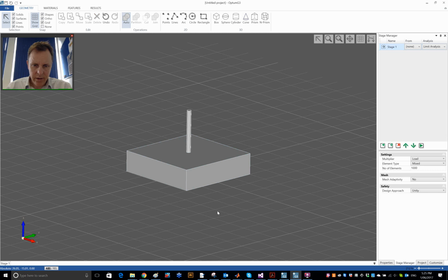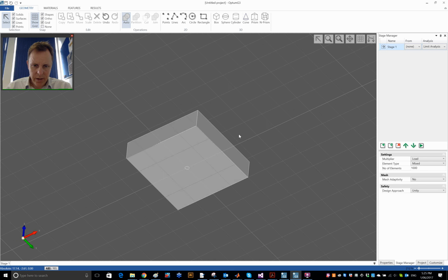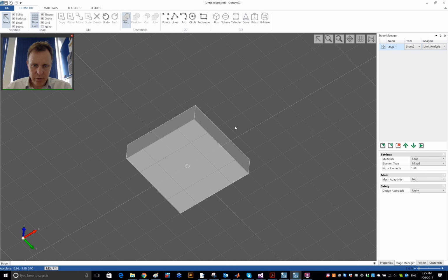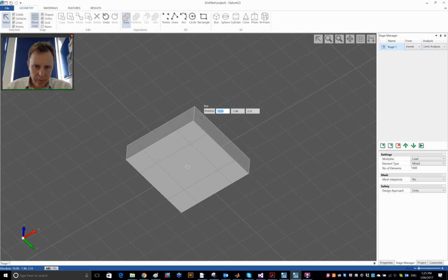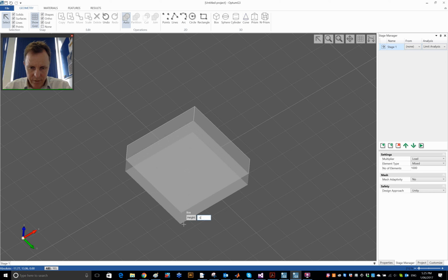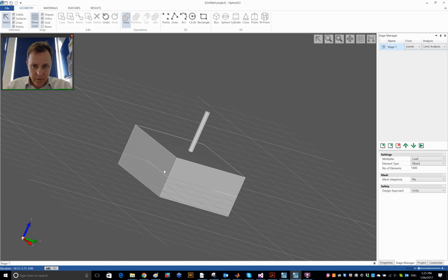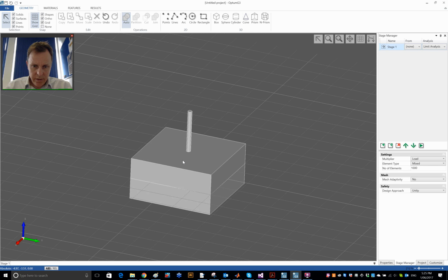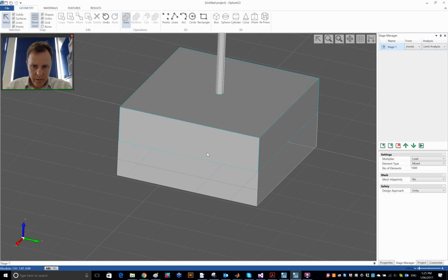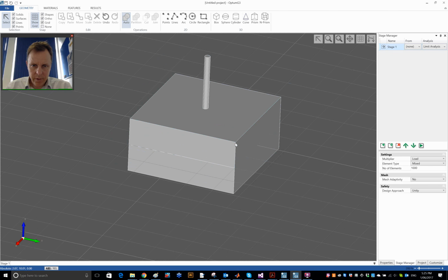the soil, and you should be able to see the base of the pile. And then we would want some soil here as well below the pile, and again I can make that to a depth of 5 meters. So I enter a height of -5. So here is the complete problem, complete geometry.